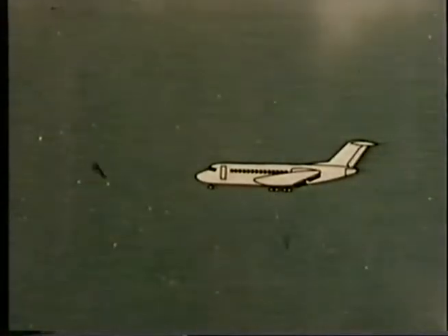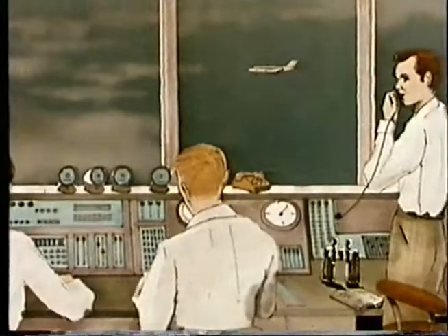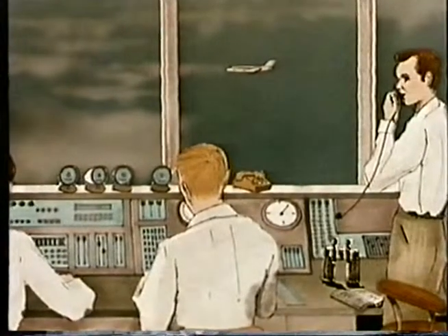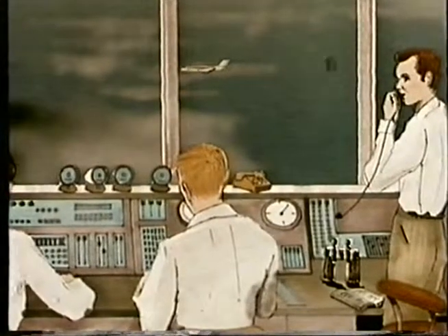Should an aircraft enter a traffic circuit without proper authorization, in case of radio communication failure, for instance, it shall be permitted to land if its actions indicate that it so desires.